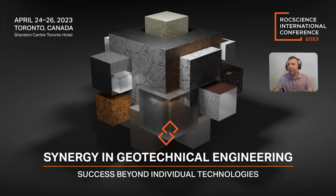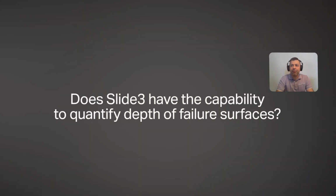The other technical question was, does Slide3 have the capability to quantify the depth of failure surfaces? Yes. We added a new option last year, the column depth option. You can look at the contours of the column depth, which shows the depth of a slip surface at different locations. Also, after the analysis, you can look at a lot of information in the project report generator, including the slip surfaces, the depths of slip surfaces, volumes, and this kind of information.